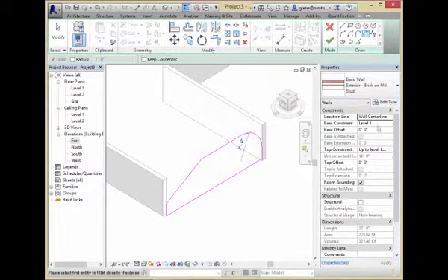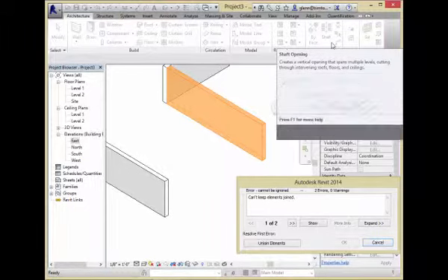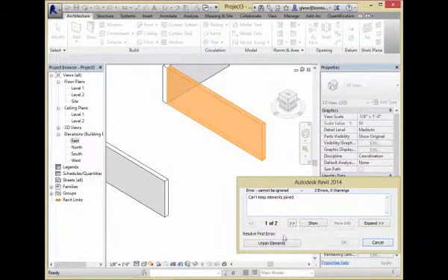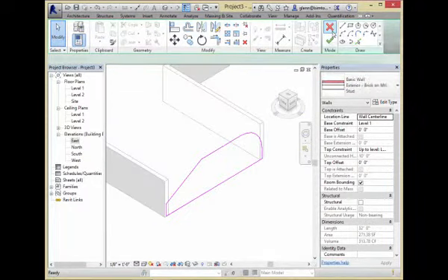Okay, so if we round that off, we can make a wall. Oops, that's interesting. It's complaining. It doesn't quite like something there. Let me say unjoin it. I think what it's a little unhappy about must be something about the join of this wall to that wall. What used to be this nice mitered corner now is all rounded off, and it can't figure out how to miter exactly. We could also edit that and just put holes in the wall.